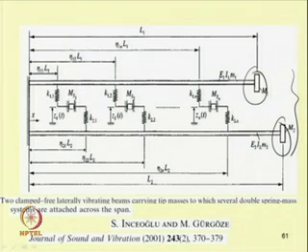So, without complicating the system, by taking only a single mode approximation one can have two equations, and by taking these springs to be nonlinear one can derive this equation of motion, or by taking this beam to vibrate with large displacement as in the present case. One can study the equation with and without internal resonance.